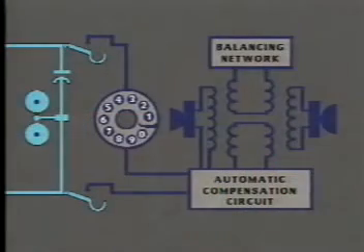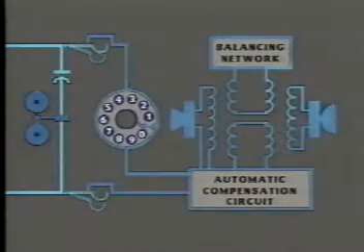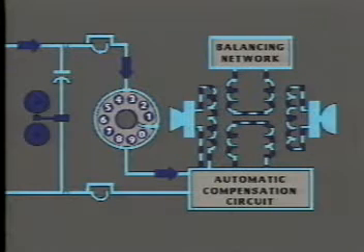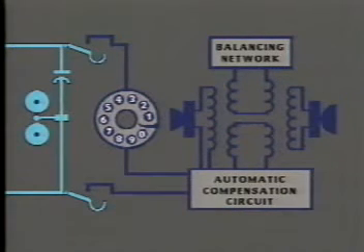Next, let's briefly discuss the switch hook, which opens and closes a set of electrical contacts inside the telephone. When the handset is lifted from its cradle, the switch hook contacts close, permitting direct current to flow from the central office through the access line to the telephone set. But when the handset is resting on its cradle, only the ringer is able to operate.